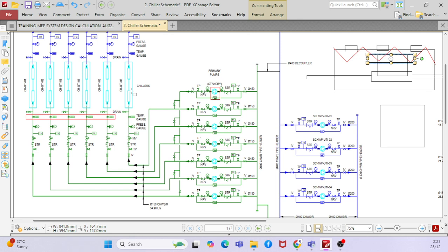When you run the chilled water flow, that chilled water will get all the necessary cooling from the refrigerant. If you don't supply the proper flow rate while the compressor is running, the efficiency of the chiller will go down, right? So the primary pump will supply the required flow for the chiller. Clear, right? Say for example, if this chiller requires 50 liters per second, this primary pump will make sure it takes the flow of 50 liters per second and supplies it to the chiller, right?